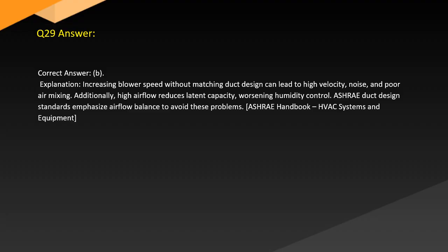Answer. Correct answer: B. Explanation. Increasing blower speed without matching duct design can lead to high velocity noise and poor air mixing. Additionally, high airflow reduces latent capacity, worsening humidity control. ASHRAE duct design standards emphasize airflow balance to avoid these problems. ASHRAE Handbook, HVAC Systems and Equipment.